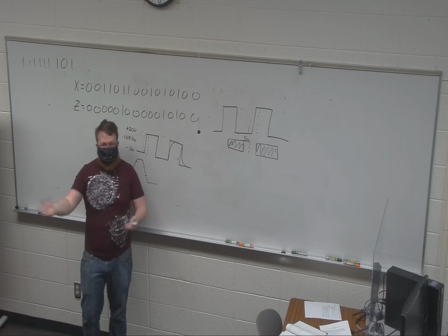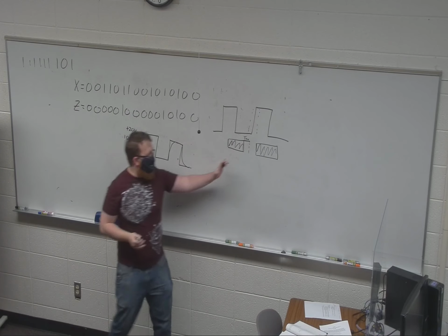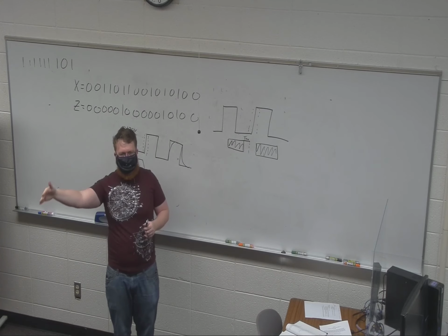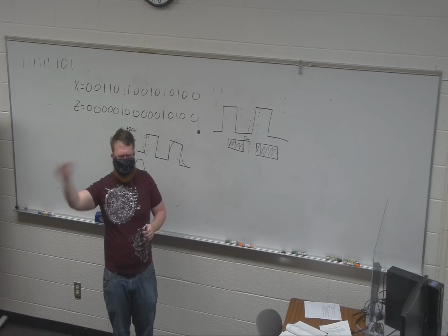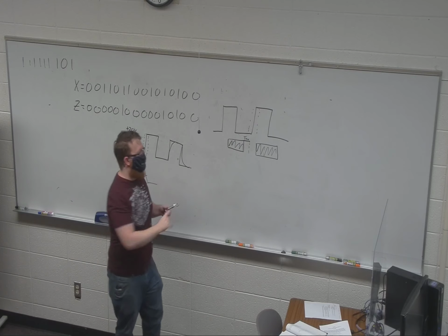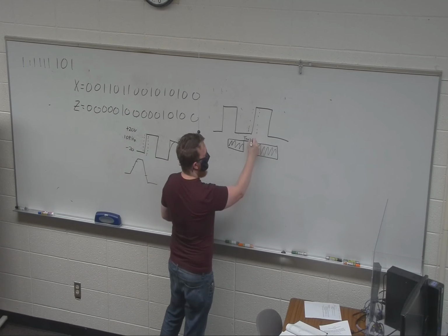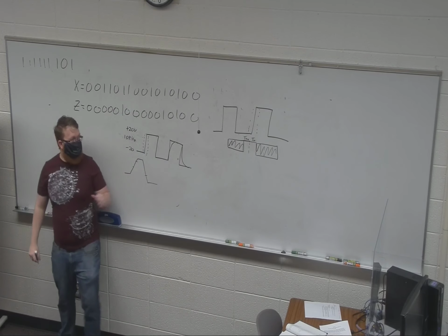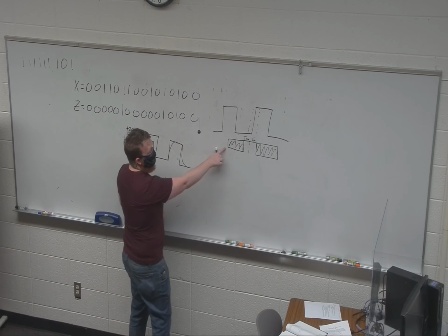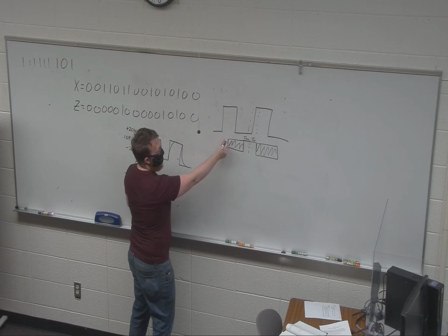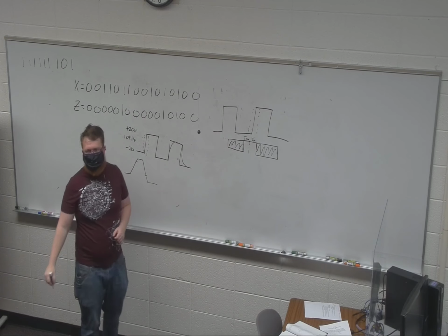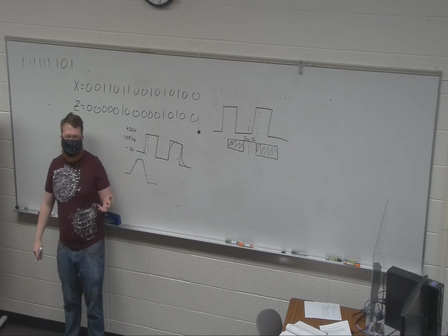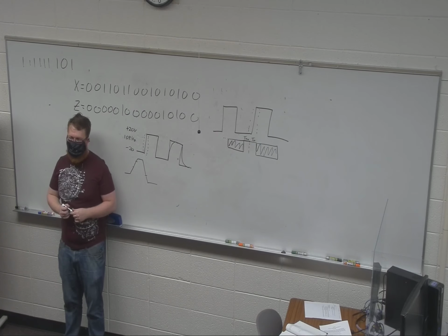And then these flip-flops don't record it instantly. So you could set it up and then change, and you're going to capture some voltage in between on and whatever your next data, which it might be okay, but if it's changing, it might not. So we also have TH, hold time. So those are your two, setup and hold. And you'll notice this stops here because now I have hold time from the last one. So that's your timing. You're going to look at setup and hold time requirements of your flip-flops.